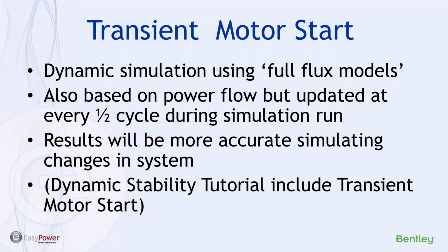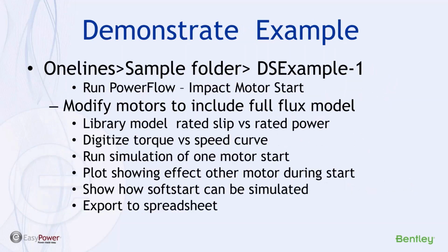And so I've included in the handout the dynamic tutorial that includes motor start and the sample file that I'm using if anybody should want to try it out. You need the demo tools or at least access to the transient motor start module. But as I say, this is built into your system, so if you go look into the tutorials under power flow analysis, it'll go through this example.